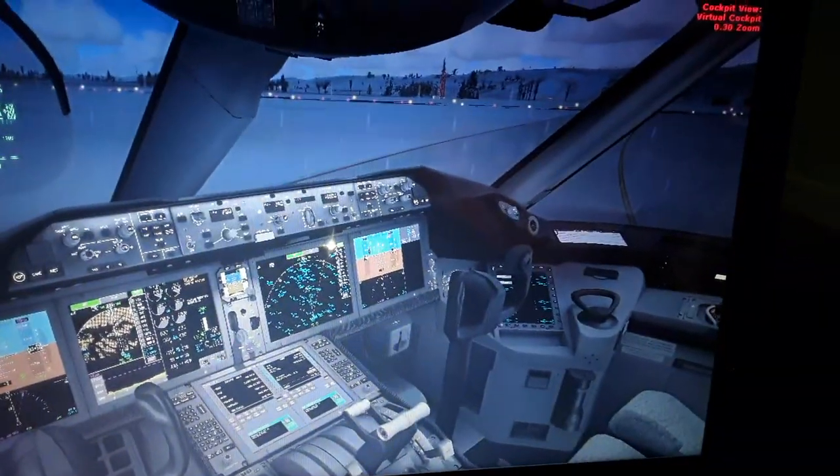So a few more things, the flight management computer, so I will input all the data we need for this flight: the takeoff gross weight plus the passengers plus the cargo plus the fuel on board, what the fuel is stored in the left and the right wing. In the center tank we have 30% in the left and the right wing and 10% in the center tank of the aircraft. Right now the flight management computer is gonna calculate the center of gravity of the aircraft automatically,